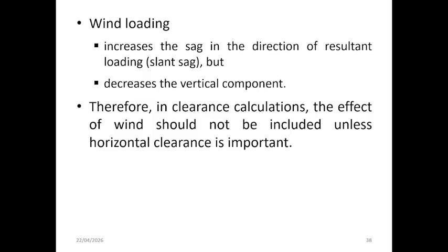Okay, this slide also explains the effect of wind loading on the behavior of overhead conductors and its implication for sag and clearance calculation. When wind acts on a conductor, it introduces a horizontal force that combines with the vertical forces due to the conductor's own weight and any ice loading.